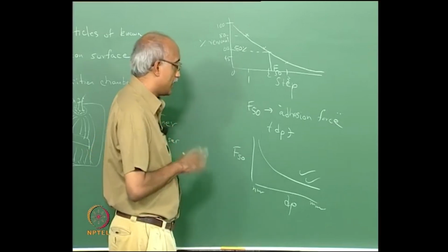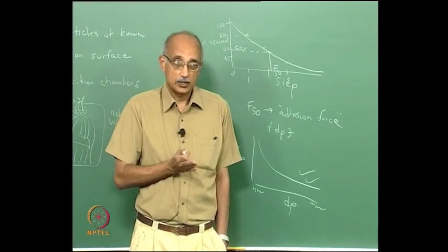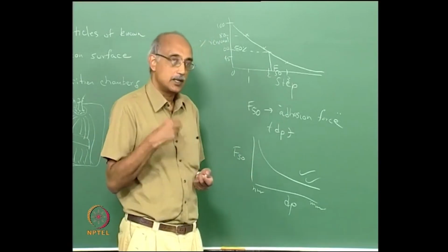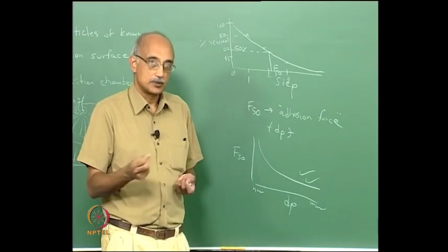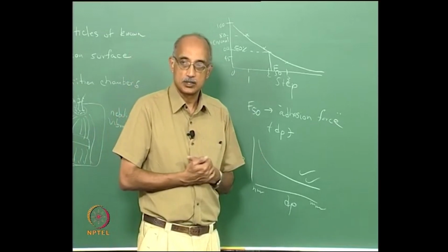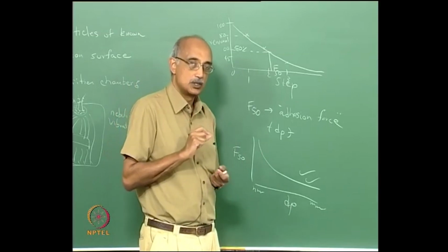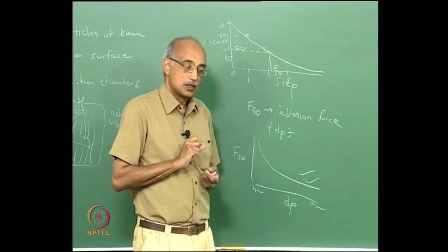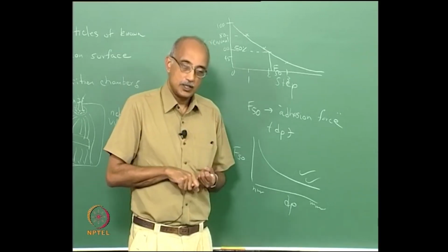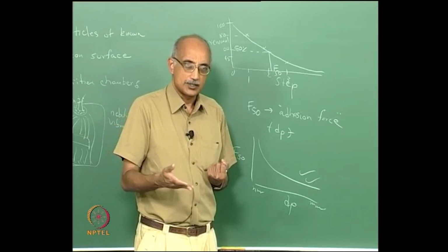So, one of the things to keep in mind is this definition of adhesion force by measuring the force required to remove the particles is also dependent on the technique that you use to remove the particles from the surface. So, this F50 that you have estimated as your adhesion force is not a unique number. It will actually depend on the method that you have used to remove the particles from the surface. So, clearly the particle removal method also plays a significant role in determining the adhesion force of the particle to the surface, but also in a practical sense.